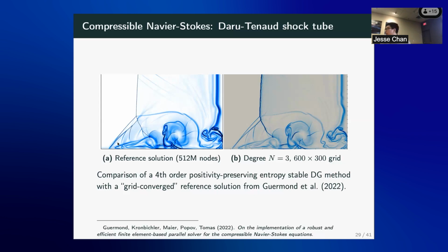No, they are enforcing a minimum entropy principle on the inviscid term only, and then joining that together with the Navier-Stokes terms. To my understanding, their completely coupled scheme for the inviscid and parabolic equations does not actually enforce any real entropy principle. It just enforces positivity of internal energy and density.